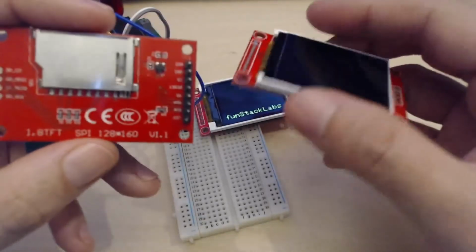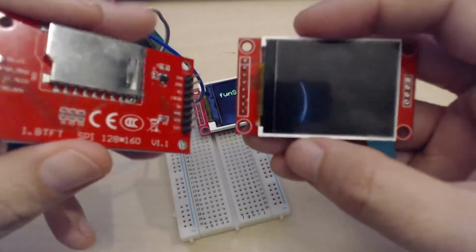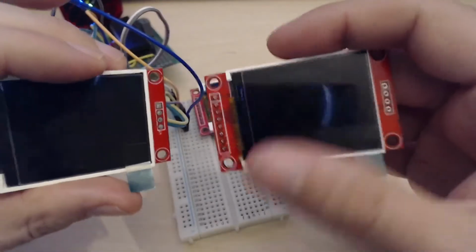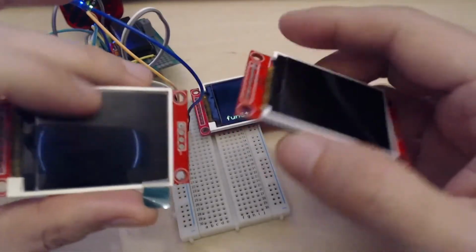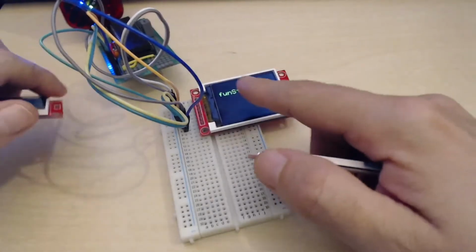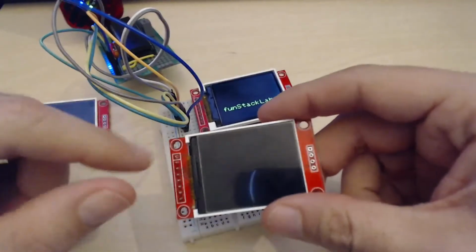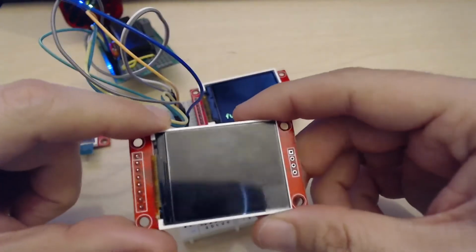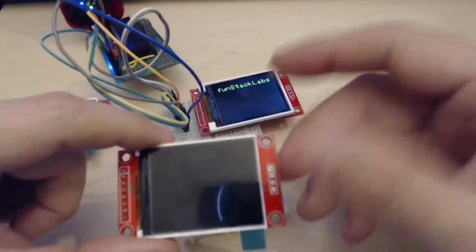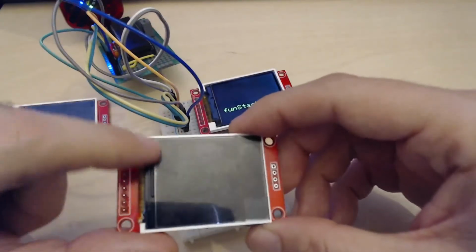They're supposed to be using ST7735S TFT drivers, both of them, but they could be knockoffs or replicas of these chips. This one works fine. You see the animation, it works fine with the driver that I'm going to show you. But with this one, whenever I push a byte to it that starts with a 0, it resets and the whole screen goes white. Then when I push another byte, any data or command byte really, it comes back to its senses and starts displaying again.